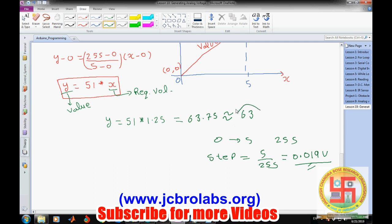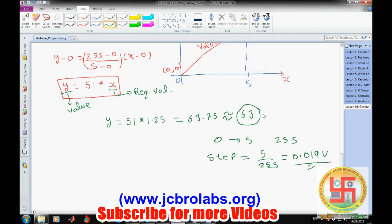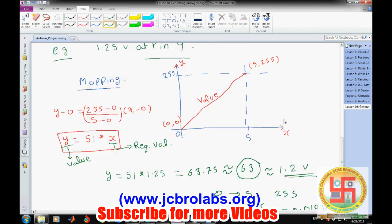Now if we get 63 as y, corresponding to 63 we can find the voltage. Total 63 steps are there, so 63 multiplied by 0.019, and the voltage generated will be about 1.2 volt. So approximately 1.2 volt will be generated at the output pin.